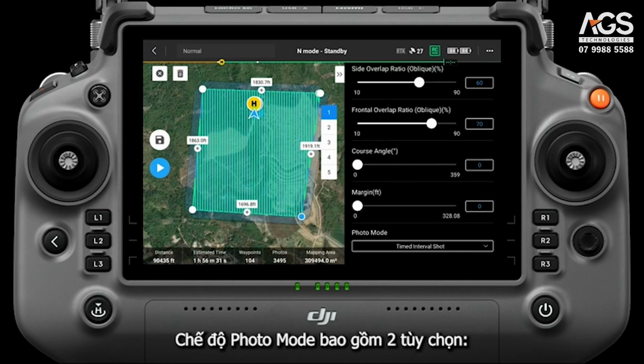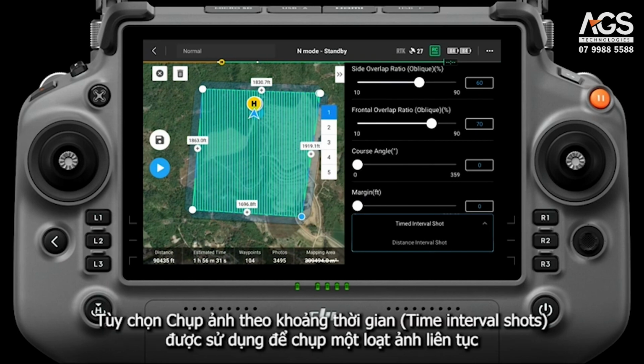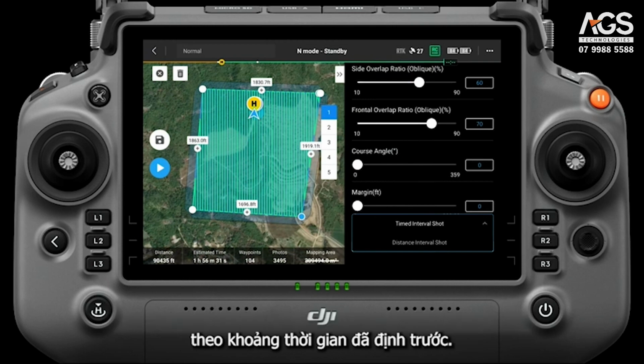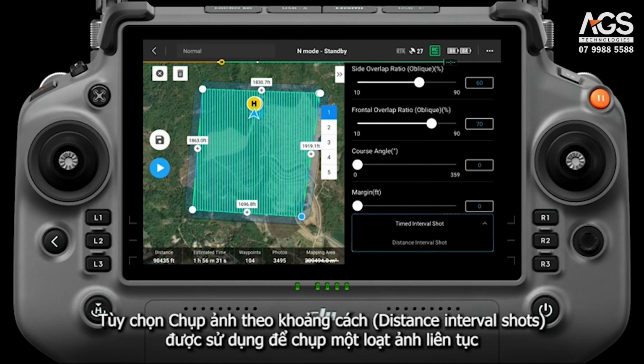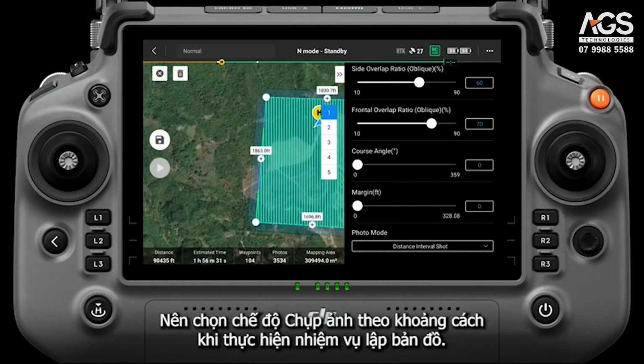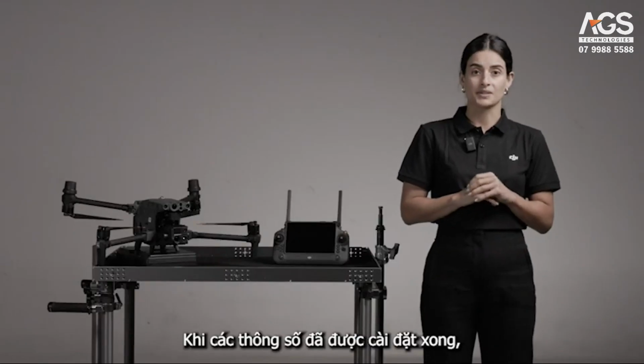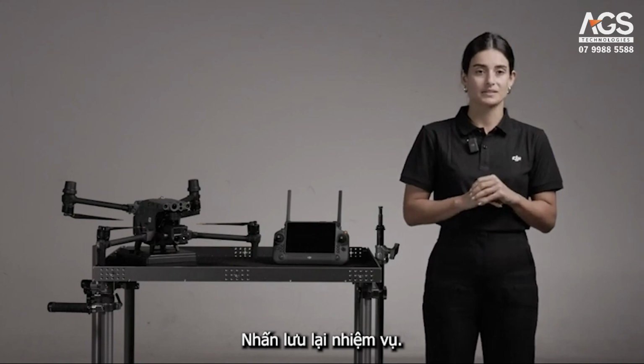Photo mode includes time interval shot and distance interval shot. Time interval shot is used to take a continuous series of photographs at each specified time interval. Distance interval shot is used to take a continuous series of photographs at each specified distance interval. It is recommended to select distance interval shot mode when executing a mapping mission. After the parameter settings are complete, save the task.